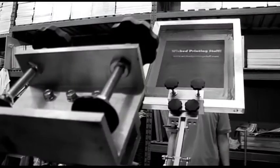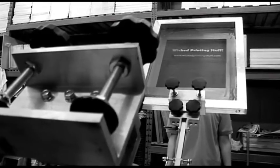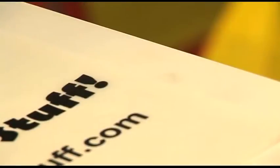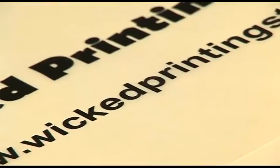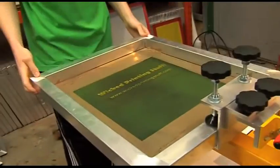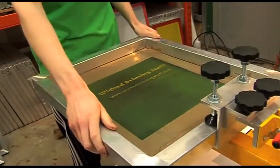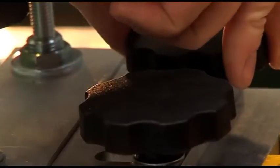Firstly, you need to set your screen up on your press. You must adjust your screen before fully tightening it into place. You need to ensure your logo is in the right place for your garment. We want our design in the centre of the t-shirt, so we place and tape our artwork onto our platen where we wish the logo to fall. Then line your logo on the screen up with the logo on your artwork. This is fairly straightforward as we are only printing one colour and do not need to be precise.